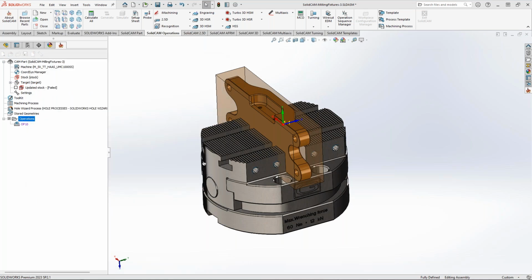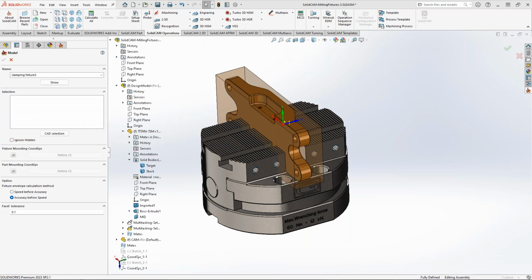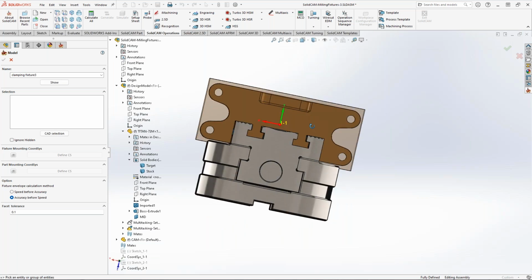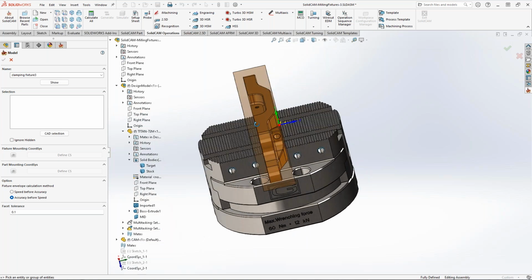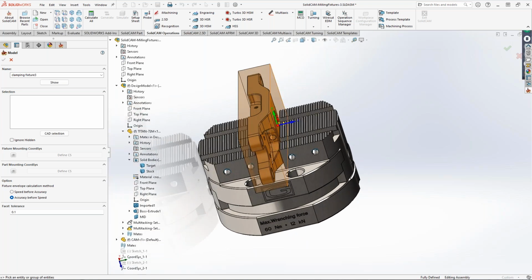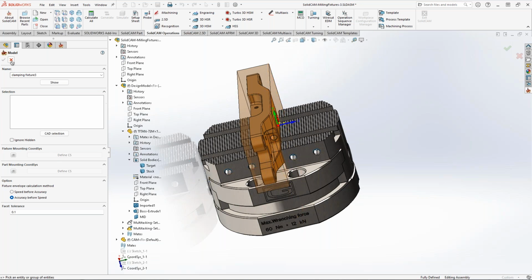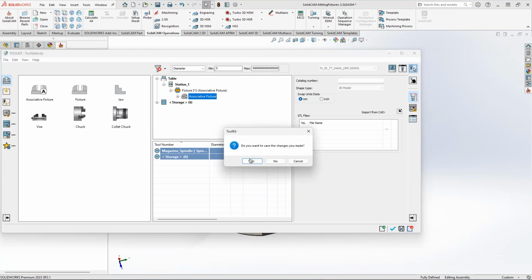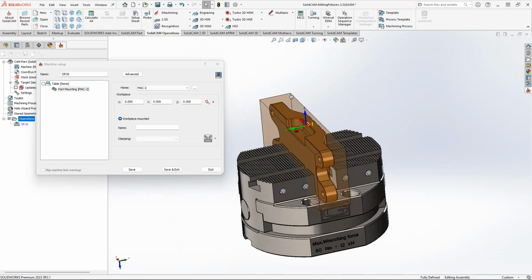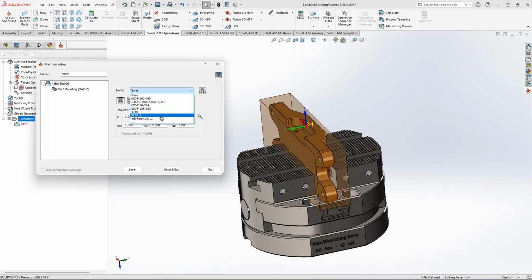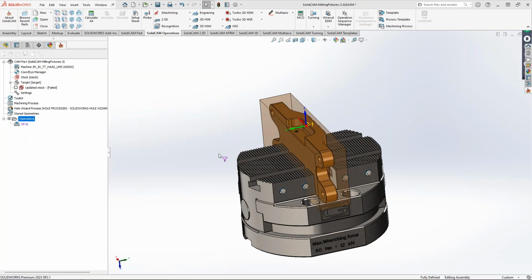And again, I'm going to pick from CAD. Obviously, this time it is a different CAD, but what is a mistake? I'm still having Mac 1 position 1 active. And this is where most users make a mistake, because now the new assembly is going to be based on this coordinate system. So I'm not going to make any changes, but before that, change Mac 1 to Mac 2. Now when I have the active Mac, I can go back and repeat the process.